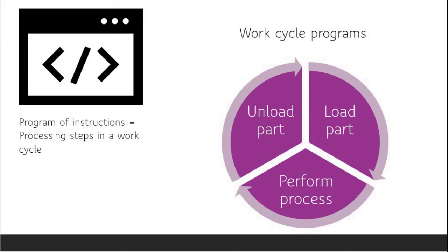So process parameters basically refer to inputs of the process such as temperature setting, coordinate axis value in a position system, whether a valve is open or closed in a fluid flow system, or motor on and off. Okay, so process parameters or the inputs are distinguished from the process variables. Process variables refer to the outputs of the process, for example, the actual temperature of the furnace, the actual position of the axis, the actual flow rate of the fluid in the pipe, and the rotational speed of the motor.